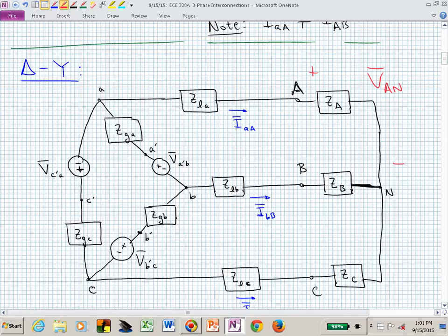The line current is really the current on the transmission line between little a and capital A. That's always the line current. But in the load, is it the same as the phase current? And in this case, in the load configuration of Y, it is. But if we went back to the source, then our phase currents at the source are not equal to the line current. Question?